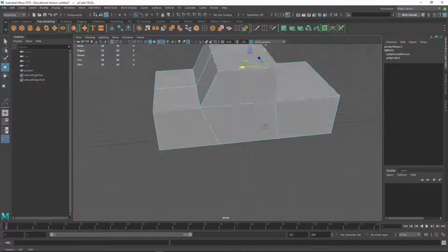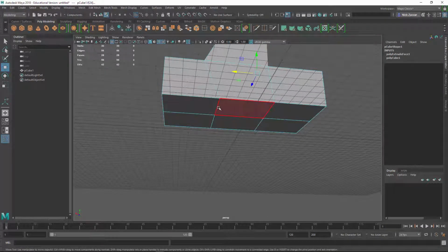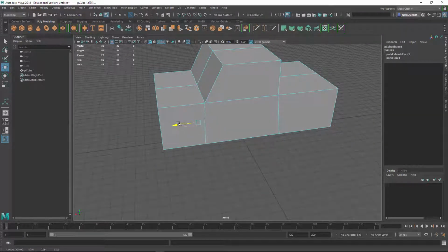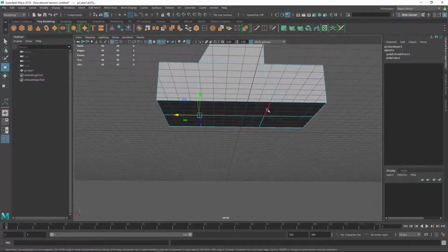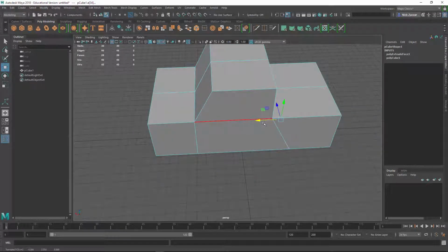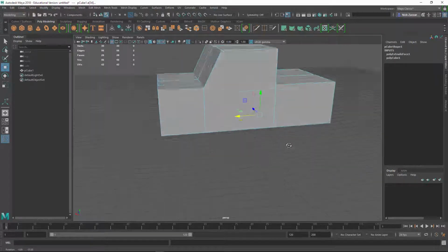Okay, now if we want to straighten up these edges, we can hit F10, or right click and say edge, multiple ways of doing this, and we can move this along through here. So you can eyeball it, but if you hold down V, if you remember from looking up here in the interface about snapping to points, if you hold down V and just move along this axis right here, you can move these back and it'll snap to wherever you are on these points. So let's go to these edges here and move them, and I'm going to hold down V and snap right here like that.